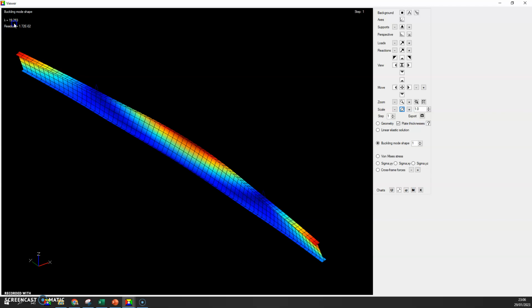So again, we've got 3 limit states to check. Usually the end rotations, this is to avoid fit up problems, they should be less than 1.5 degree in general. That's the recommended value. We should also check eigenvalues. They should be above 1 to avoid stability issues, and 1 is not enough. If it's 2 or 3 or 4 or 5, that's even better. 1 is too small, and 2 is probably also slightly close to 1. And the other thing would be to check stresses. The value of Fy over 2 is recommended.